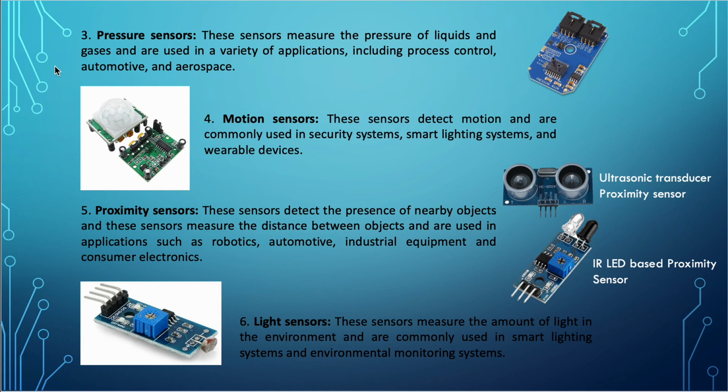If somebody comes to you and says, we want to automate this part, we are pumping petrol from this location to another location through an underground tube, and we want to check the pressure when the oil is traveling through that tube, the first thing that should come to mind is a pressure sensor. But when designing, you should be able to understand that we are talking about a liquid, and we are not talking about air.